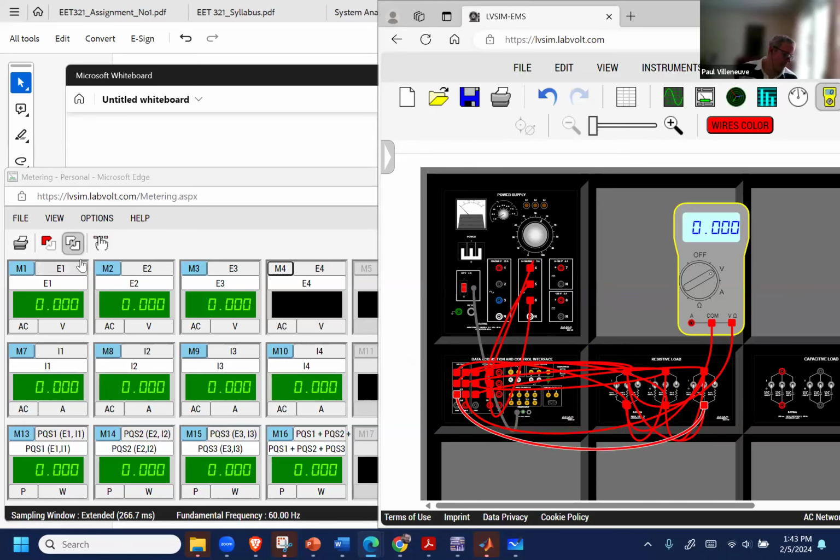bottom of this resistor. So now when I turn on my power supply, I'm measuring the same voltages I measured before because the line and the phase voltages are the same, right? I'm just looking across the top and the bottom, which is the phase. And now I've got my voltages, my currents, and now I can calculate my power. So it's not this times this, it is this voltage times the 400 milliamps that we did before. Same thing here and here. And that's what I get for my powers over here.